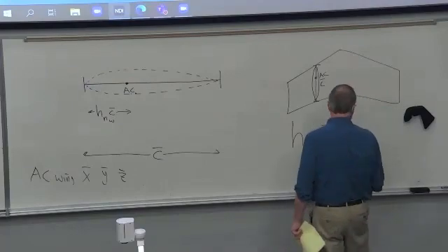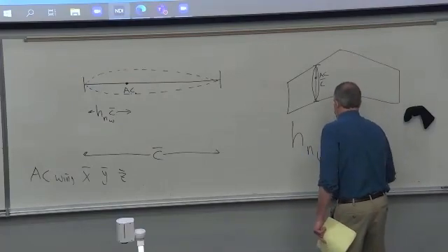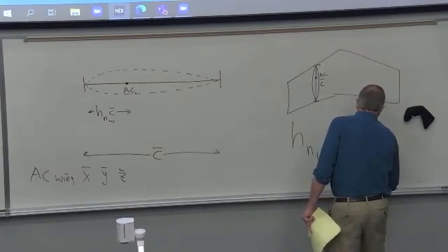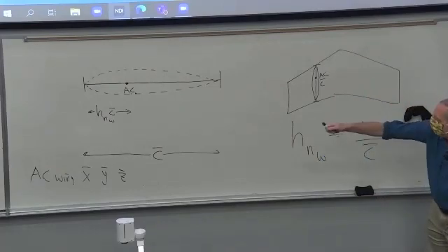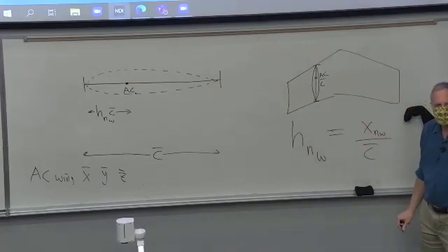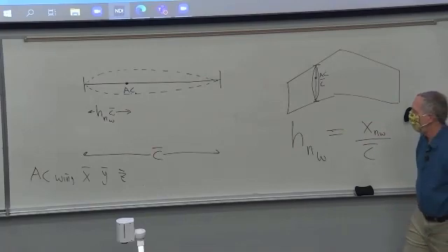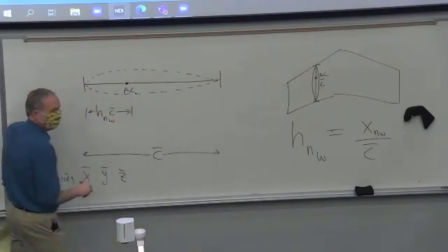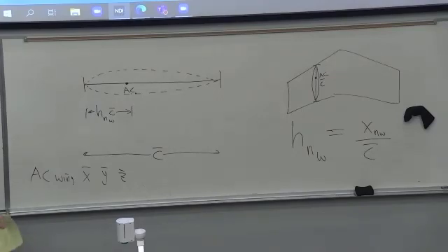So H N wing is actually the distance X bar back divided by C bar. Because to get that distance, we have to multiply it by C bar. But we'll always do it in terms of this non-dimensional distance H multiplied by C bar. So if you are doing a problem and you write H N wing equals 5 feet, you're not right. It's just going to be 5, and then you have to multiply by C bar in feet or meters to get the actual distance. Okay, so that's step 2.